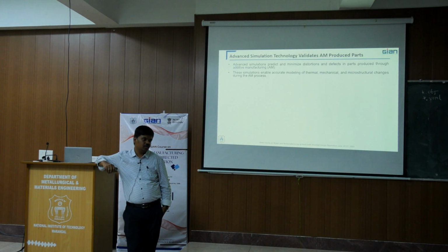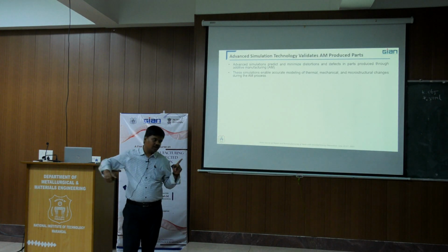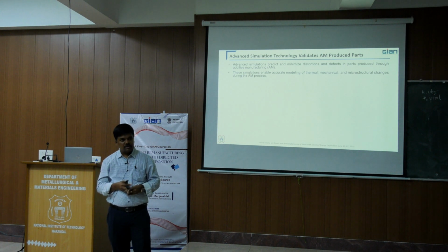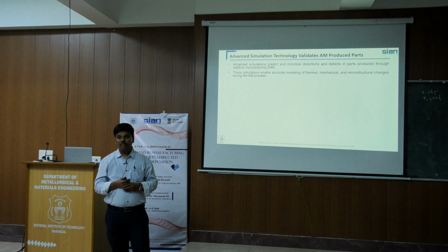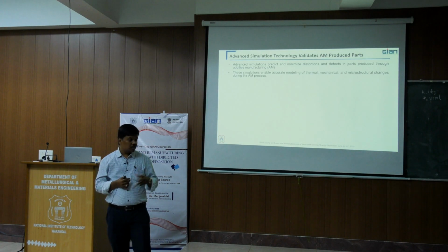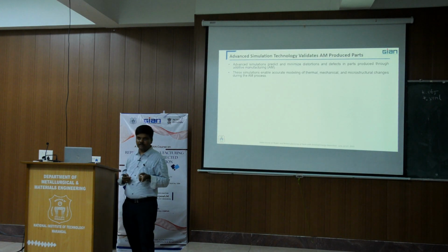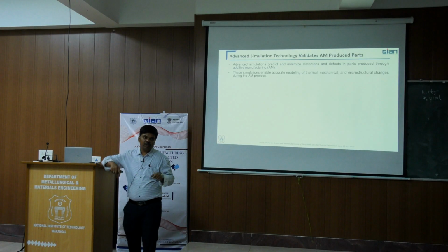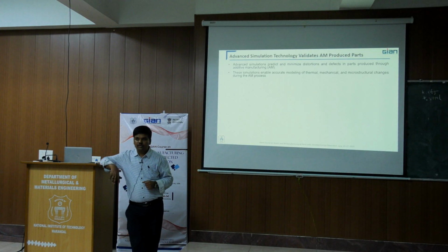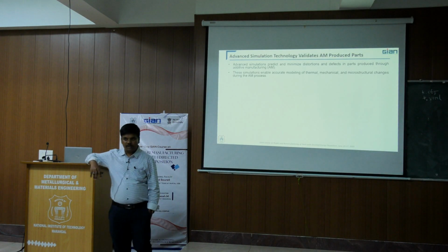What are the challenging issues we are facing? Is it only the process conditions, or the part print orientations, or the deposition strategies? For a simple, completely solid cube, you can optimize a lot of deposition strategies and scan patterns, such as hexagonal, linear and bidirectional, and you can get the best density.